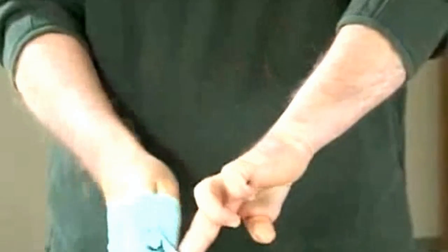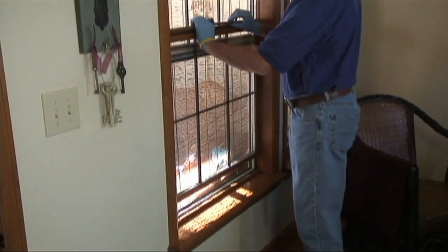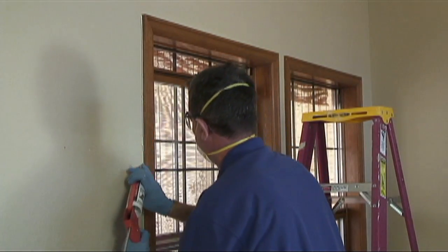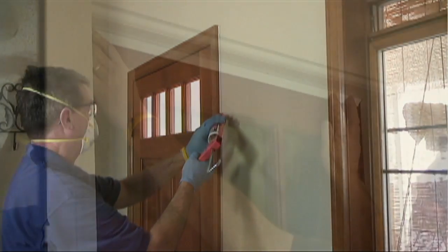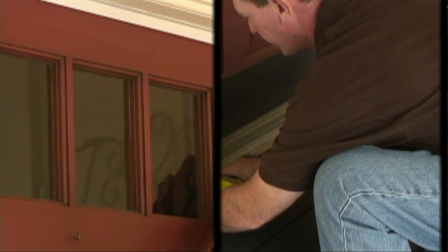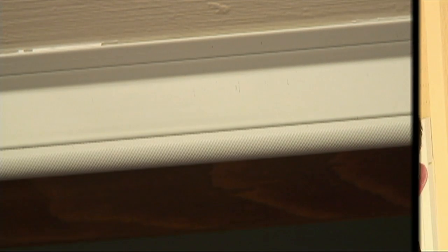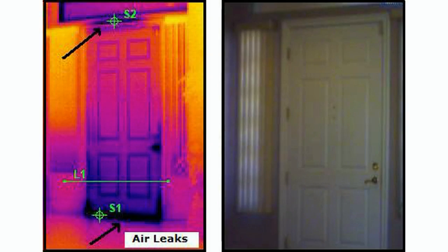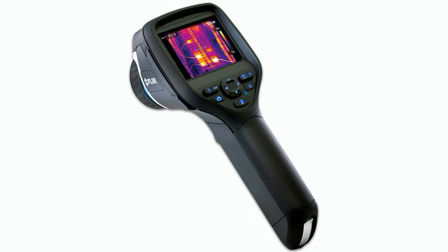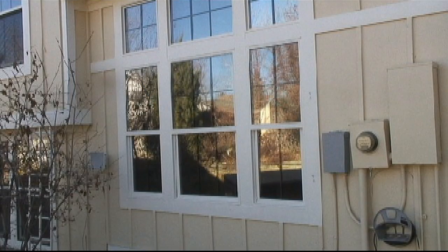When your caulking and air sealing project is complete and you have inspected your own work, you may dispose of the gloves and your excess waste materials in your normal plastic garbage bags and containers. After completion of your project, be sure and clean the entire work site and call your Weatherization Pro home performance dealer to come back and retest for air leakage with their blower door and other home performance diagnostic equipment. The air sealing and caulking on your home should be tested and evaluated every 2 or 3 years, depending on the part of the country in which you live.